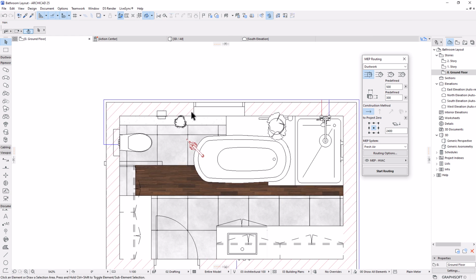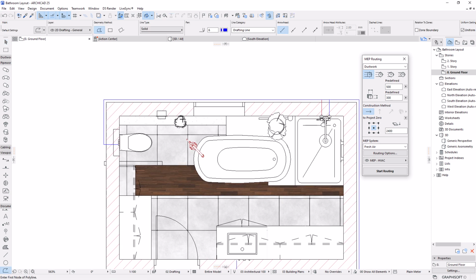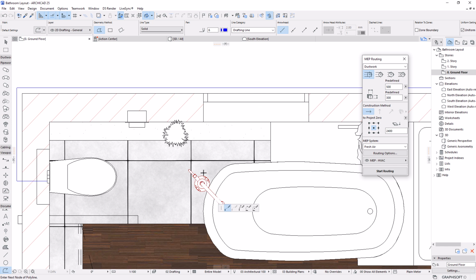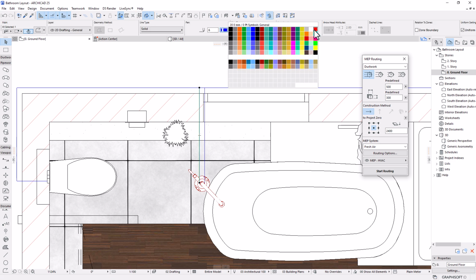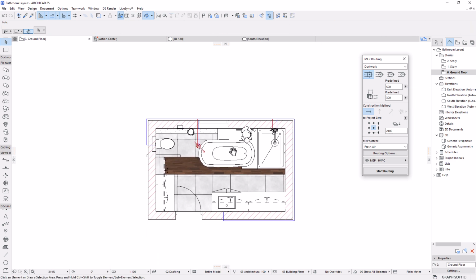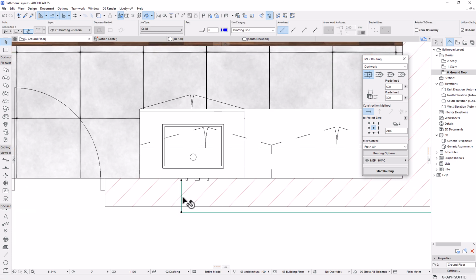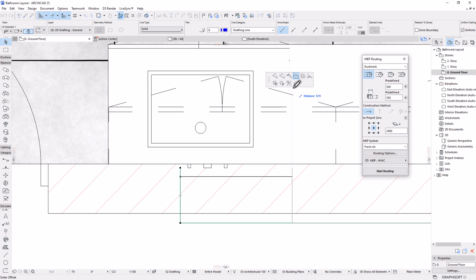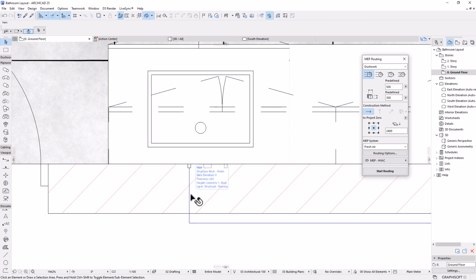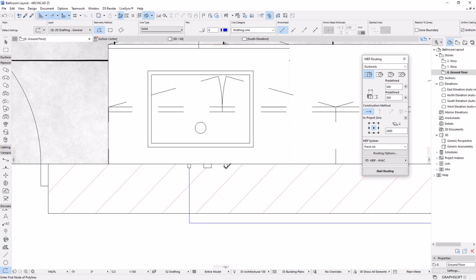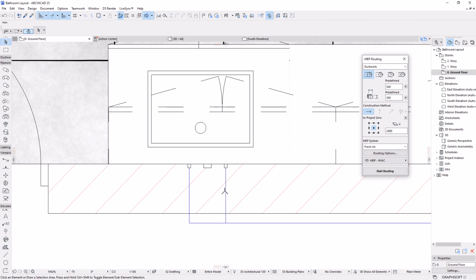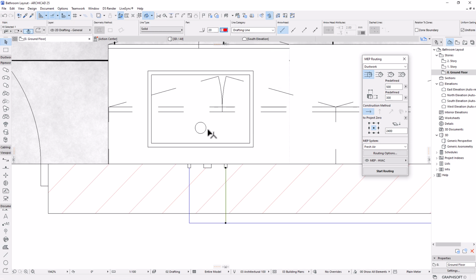Here we have both cold and hot water again for this element for the facade. I'm just going to draw over like that. Change this to color red, and oh, we need to fix this issue. I'll just pick this line and then offset the edge, align it to that. So let's again draw a line from the hot water connection point, set this line to be red like that.